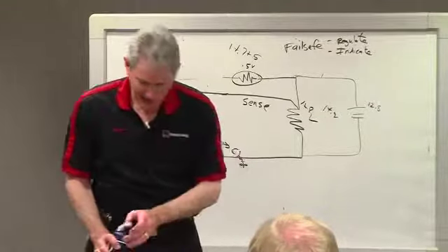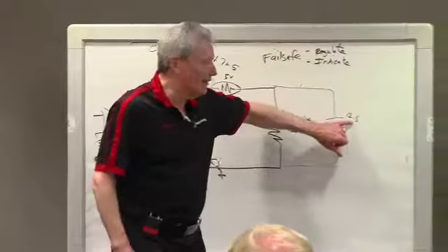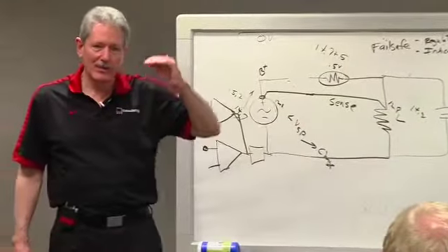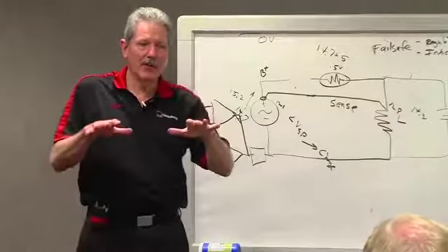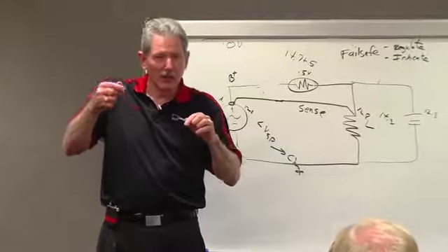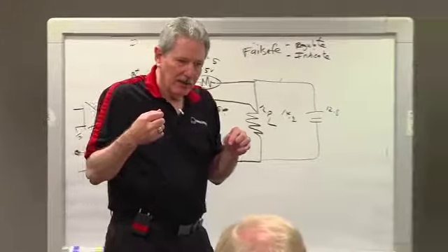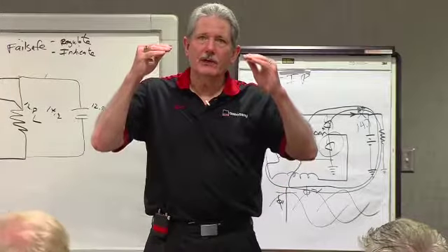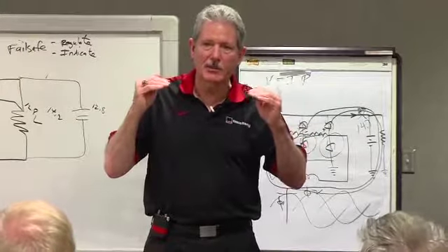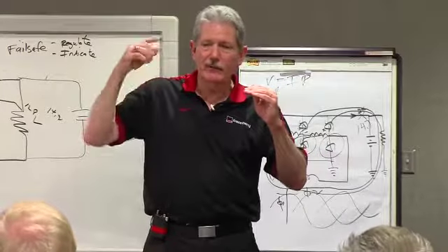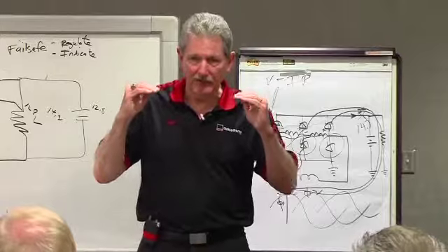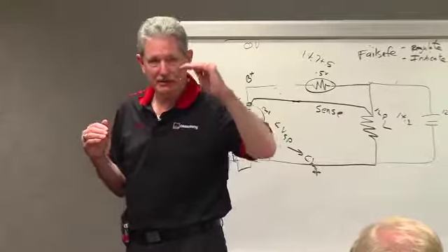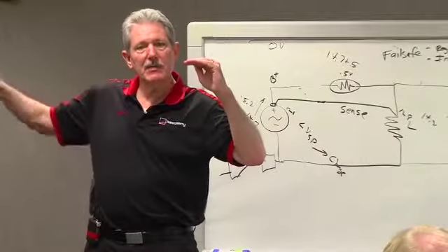So undervoltage is about, remember, this is 12.8 open circuit, 11 volts, 11 and a quarter plus or minus a quarter is where the battery has lost its life. So you want to indicate that. But you don't want to indicate it all the time. And here's why. If a transient load is put on at low speed, your alternator is going to go to full field and the voltage is going to droop a little bit. So the undervoltage was conditioned with two parameters. One is low voltage, that 11 volts, but the other is high speed.